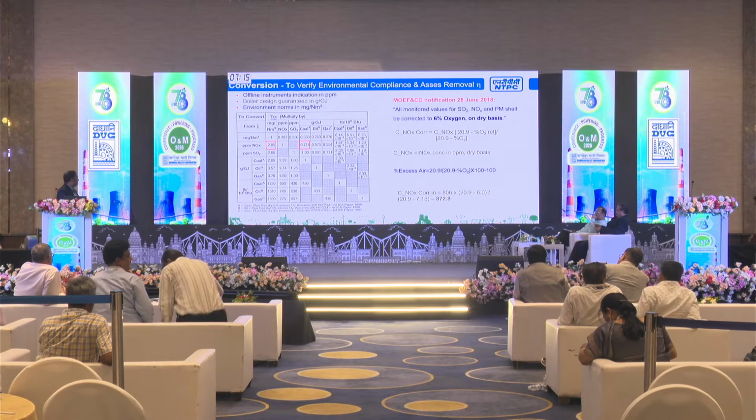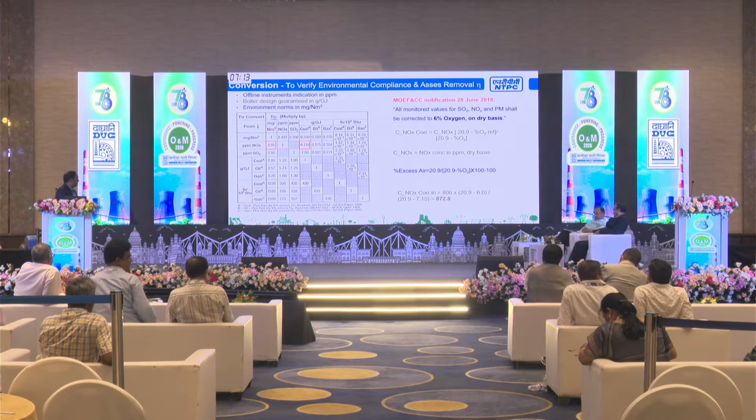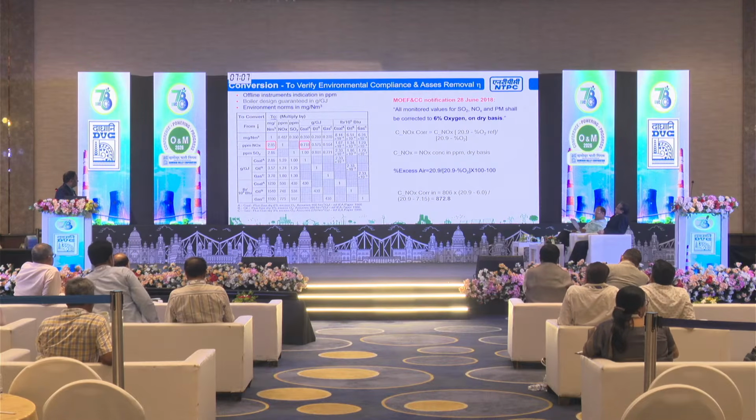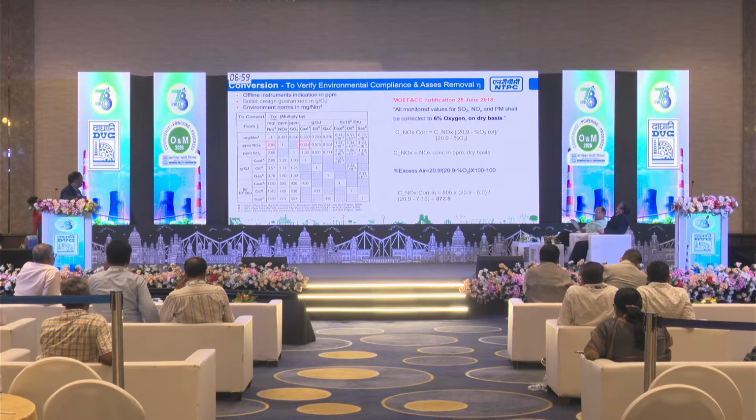Generally for offline instruments, we measure NOx in ppm, which can be converted into mg per NM3 by multiplying by a factor of 2.05. And generally the OEM, the supplier, provides the NOx guarantee in gram per gigajoule. So we can convert as and when required.